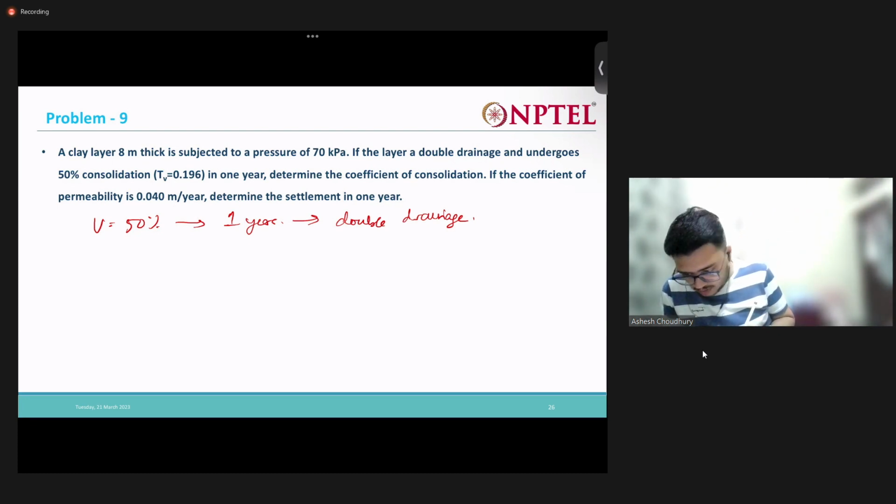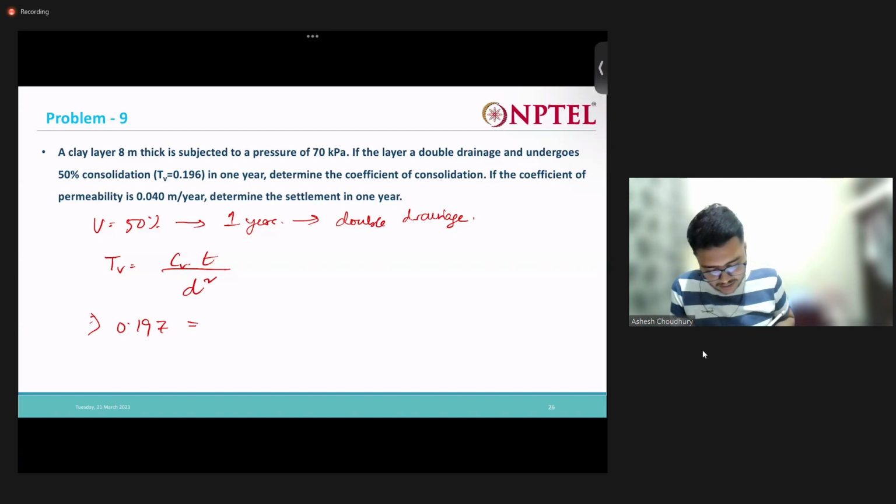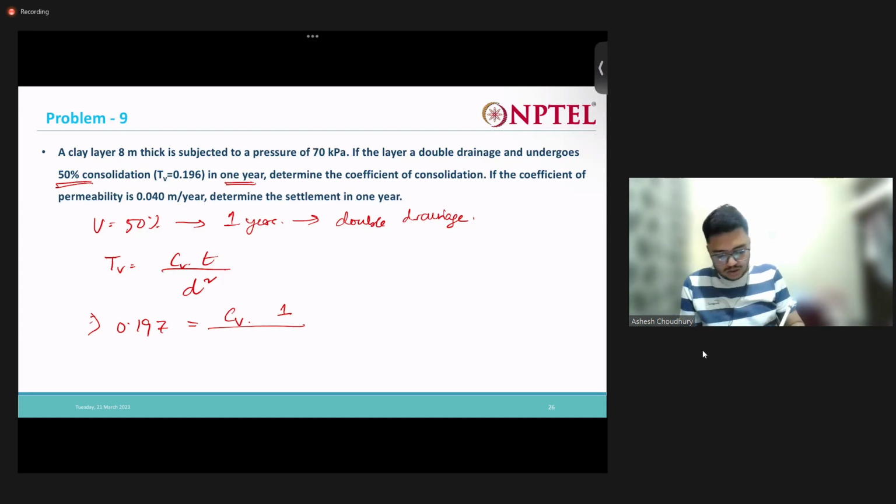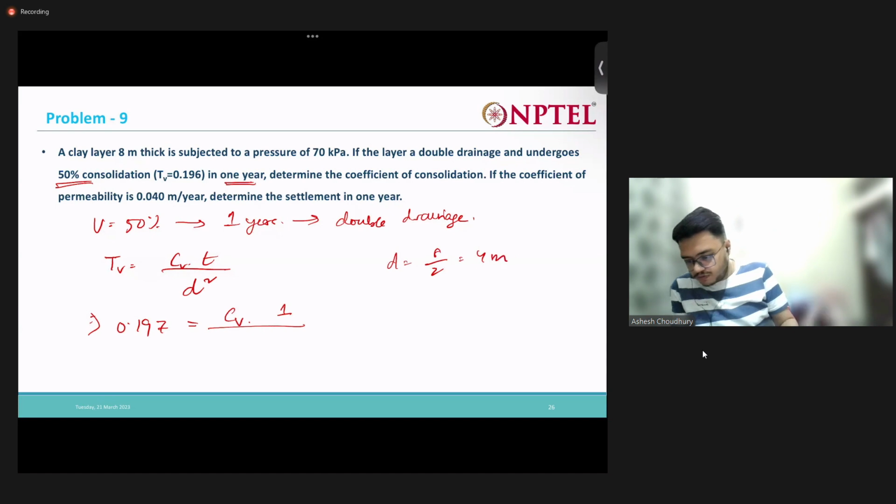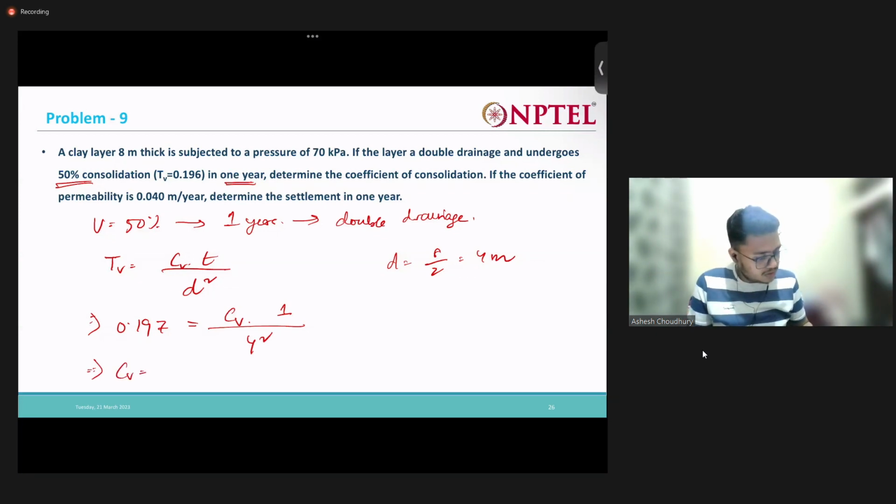So what is Tv? For 50% it's 0.197. You can type 0.197 also. 0.197. Cv I don't know, right? Cv I need to determine. What is the time? It's 1 year, because in 1 year 50% consolidation is occurring. And what is the drainage path? Double drainage, so 8 by 2. So H will be 8 by 2, 4 meters, right? So 4 square. So Cv is 0.197 into 4 square,